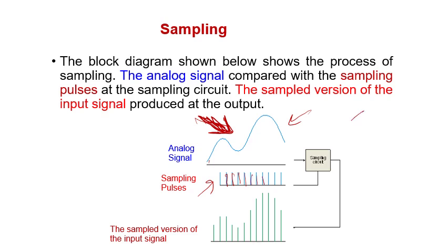such that we go to this electronic circuit, and the electronic circuit will compare them such that when the sampling signal equals the analog signal, the output will be high. Otherwise, it's going to be low. What do I mean by this? Let me put the signals together. Hopefully, you can catch them.